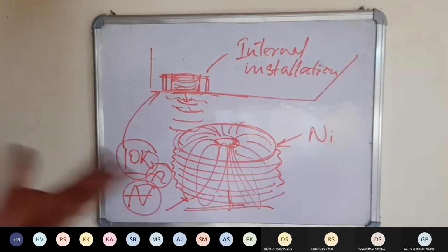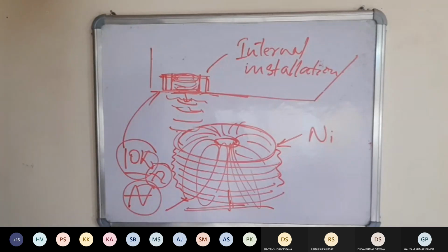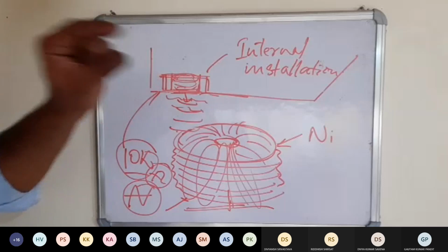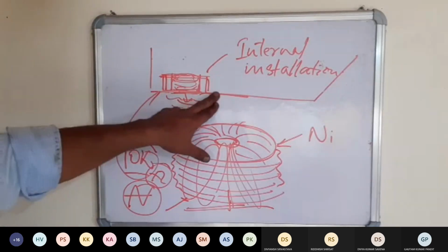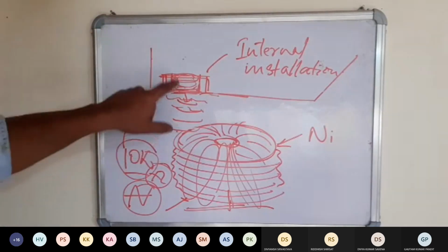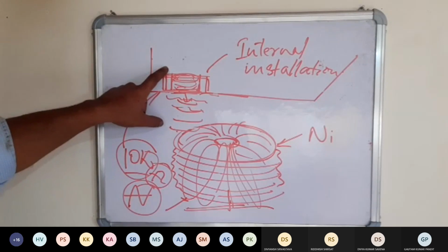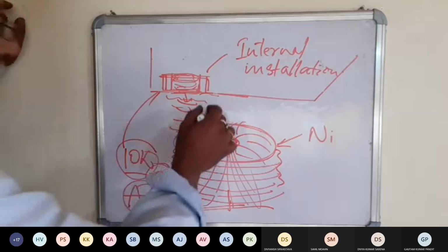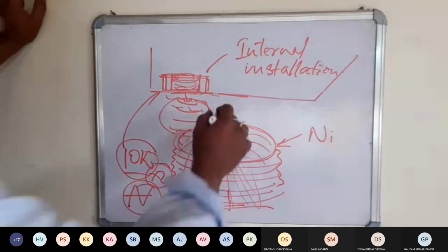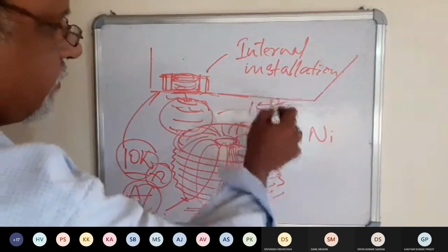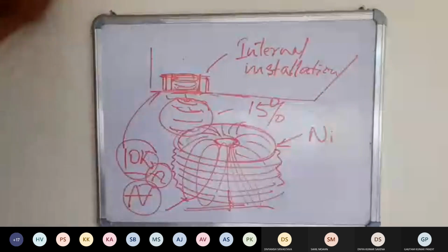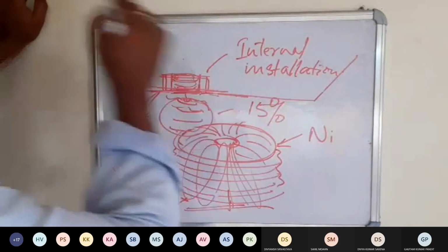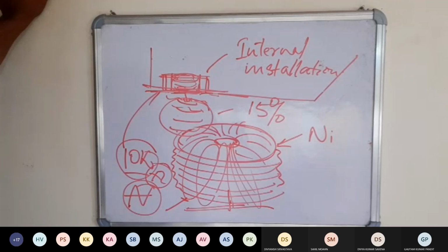But as you can think from common sense also, 10 mm, 12 mm, 15 mm की steel plate को move करने में इसकी तो जान निकल जाएगी, which happens actually. So the amount of power which is transmitted here is only about 15%. बाकी 85% यहीं पे खत्म हो जाता है स्टील प्लेट में. That means it is not power efficient.